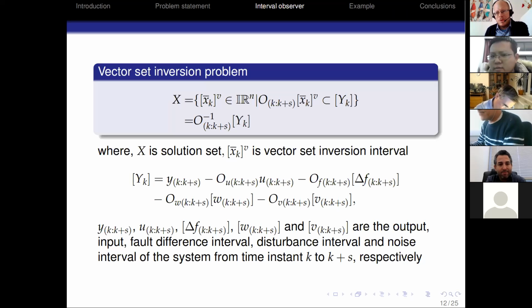In the moving horizon? Yes, because this is what you're doing, I think. Your indices here say you take a window of data from K to K plus S. In the case that your system model is linear time invariant, you could represent all the states in the window from K to K plus S as functions directly on the initial state box, state zonotope, or whatever. Why didn't you do this? Or do you think it's just something that makes sense to investigate in the future?